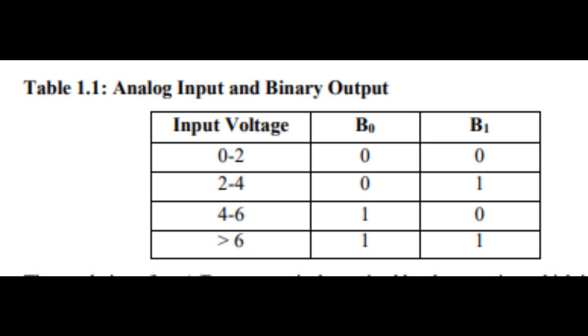The term accuracy is used to describe the worst-case error between the actual analog input signal and the recorded value as determined from the digital reading. In general, the accuracy is 1/2 of the resolution.